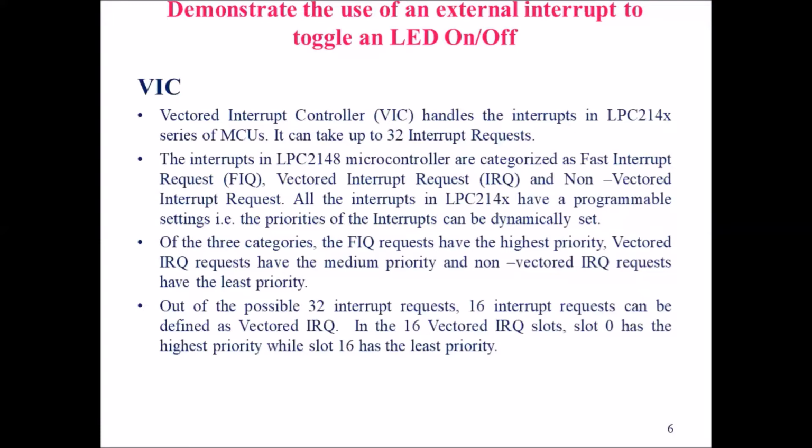All the interrupts in LPC2148 have programmable settings, that is, the priorities of the interrupts can be dynamically set. So the user can dynamically set the priorities for the interrupts to execute. Of the three categories, the FIQ, that is the fast interrupt request, has the highest priority. Vector IRQ requests have the medium priority, and the third one, non-vector IRQ, has the least priority compared to the other two.